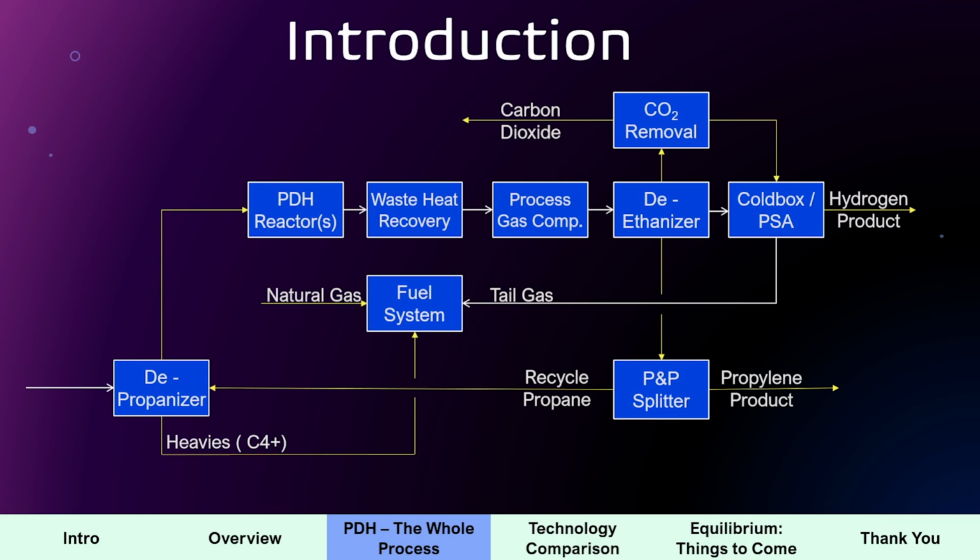So the more purity I need in my product, the higher the reflux ratio has to get. That affects the operating conditions. I'm going to have to boil and condense. I have to boil at the bottom and condense at the top an insane amount of these chemicals, because I need to purify them.